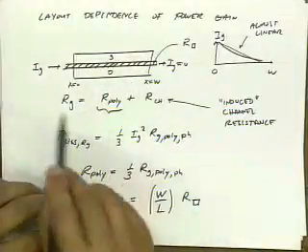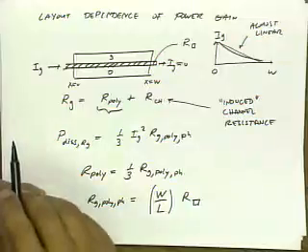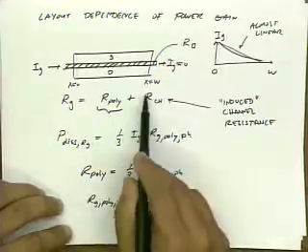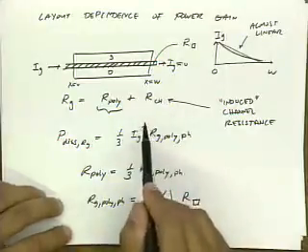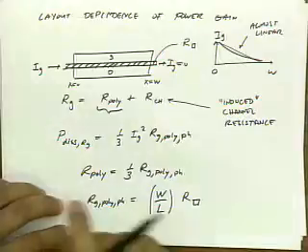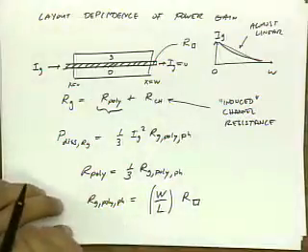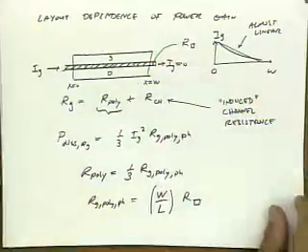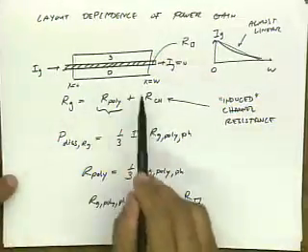And to actually analyze that problem is quite complicated. Intuitively, you would say that this should be proportional to the channel resistance. So if I go in there and look at VDS sat divided by IDS, that's roughly the channel resistance. And so this term should be proportional to that channel resistance. We'll come back to that. Let's focus on this term.